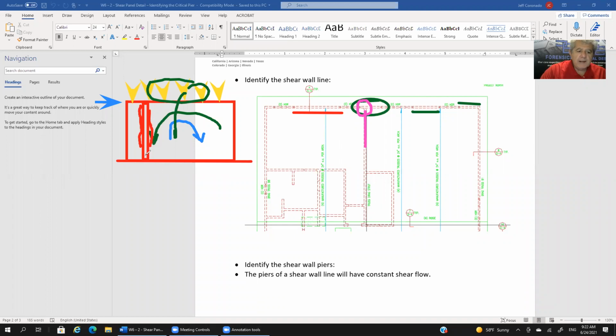This whole wall that intersects the orthogonal wall is also going to hold down, or participate in holding down, our pier from uplifting. Okay, so not only do we have the dead load from the roof weight, or the weight of the wall, but we also have this orthogonal wall that helps to anchor down our pier at this end so that it doesn't lift up at this end.